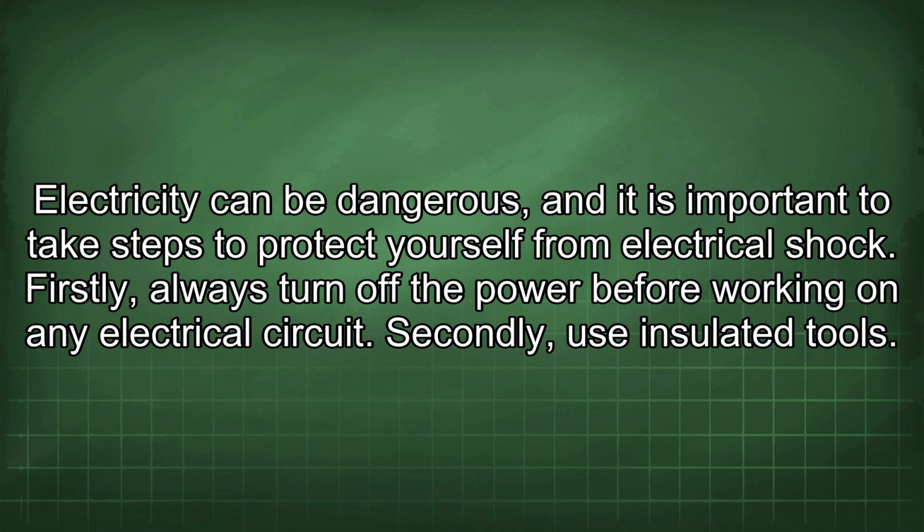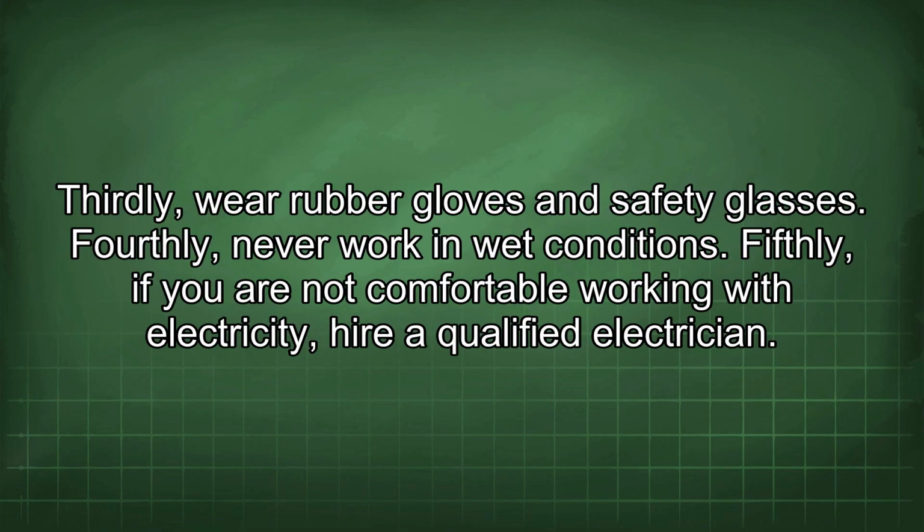Electricity can be dangerous, and it is important to take steps to protect yourself from electrical shock. Firstly, always turn off the power before working on any electrical circuit. Secondly, use insulated tools. Thirdly, wear rubber gloves and safety glasses. Fourthly, never work in wet conditions. Fifthly, if you are not comfortable working with electricity, hire a qualified electrician.